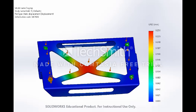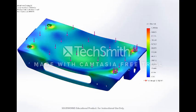The engine mount was designed using an X-mount configuration. After running a static and frequency analysis on the part, we created a design iteration for it using a completely flat plate instead of the X configuration, which resulted in much lower stress and displacement. The motor mount may not play a significant role in the overall weight of the car, but it is an option to consider when choosing between reliability and performance.